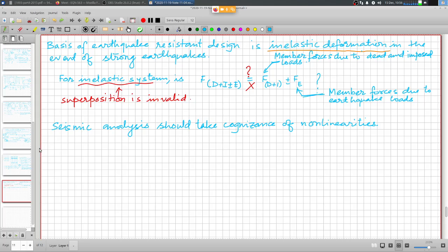Even for the elastic range, when you do not expect any cracking or any significant permanent deformation, permanent effect, right? So even the stress strain curve of the concrete, confined or unconfined, is non-linear. Something like this, right?